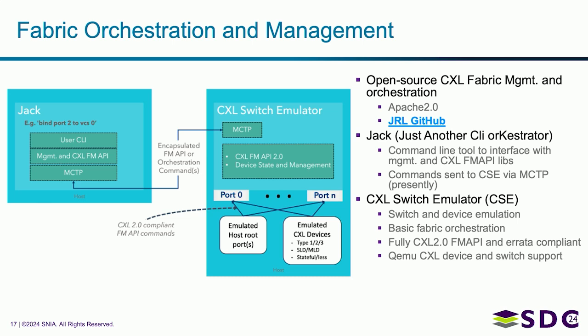But it allows you to speak FMAPI compliant commands to something that behaves like a switch in QEMU or outside of QEMU, which is why we called it an emulator to start. And it allows you to either plug virtual QEMU devices into it or real CXL devices into it and speak fabric compliant stuff to compose your memory pools and carve off resources, VCSs, stuff like that. This is all available now.